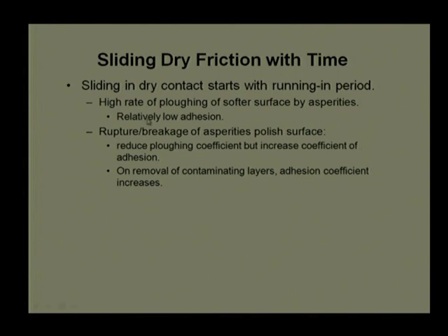If the surfaces have a super finish and are perfectly polished, then the possibility is that there will be high adhesion and low plowing effect. But we are talking about normal manufactured surfaces which have relatively high roughness. In that case, the plowing effect will be very high initially compared to the adhesion.